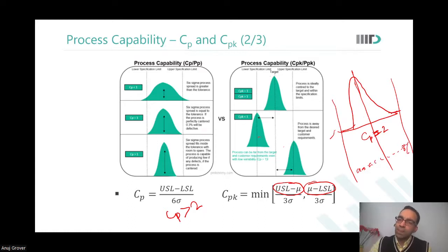But now, due to process variations, systematic variations, the length is made a little longer. So my devices are a little slower. When my devices are a little slower, let us say this curve shifts a little to the left. Now what happens? My mean is now closer to the lower spec limit. Are you able to see this?